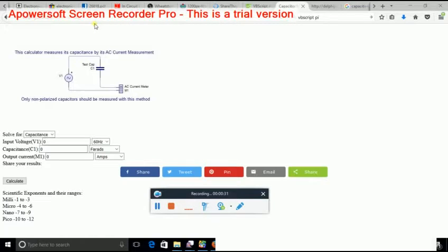Then input voltage. On the right side of input voltage, see where it says 60 hertz. If you live in a different country where it's 50 hertz, you change it, because sometimes it's not 60 hertz, sometimes it's 50 hertz. But most likely, if you're in the United States, it's going to be 60 hertz. And for our voltage we put 26.4, or whatever your transformer is, and we measured it on the meter. You want to measure it, not go by what the transformer says, because that rating is at full current. Below full current, it's going to be a little bit higher, somewhat.